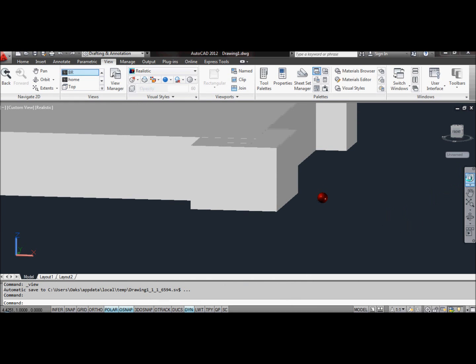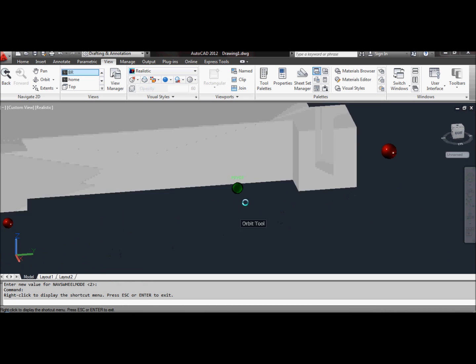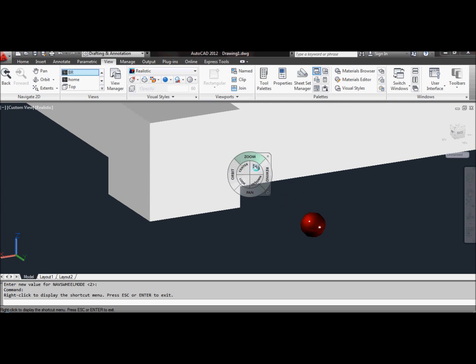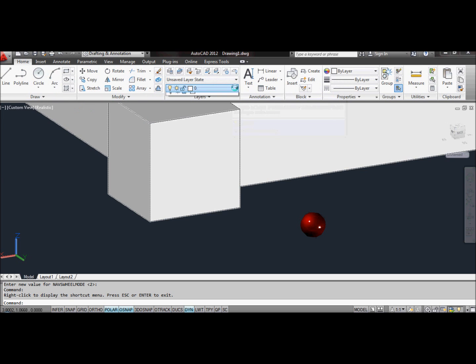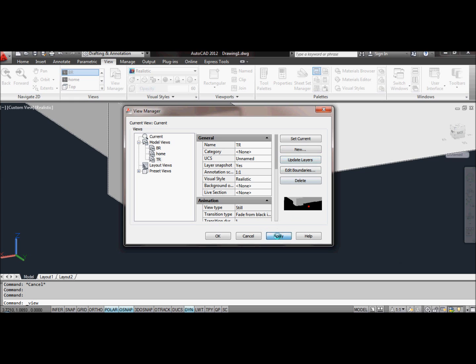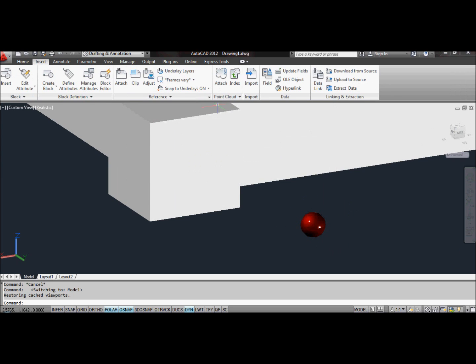There we go. Now I'm going to nip into my 3D tool again and whiz round here to another view. Now this is the top right view, but you'll notice that this time I'm looking at the upper end of the drawing, so any text I had would be upside down. Because I've changed my layers, the layer state is still the same. So my main links, which are the text that was over here, that's turned off. My home link, which is these icons here, that's turned on. I'd already placed this one here, so that's in position. So this is going to be my TR view, which is top right. There you go, and click OK. I update layers just to make sure it's updated.